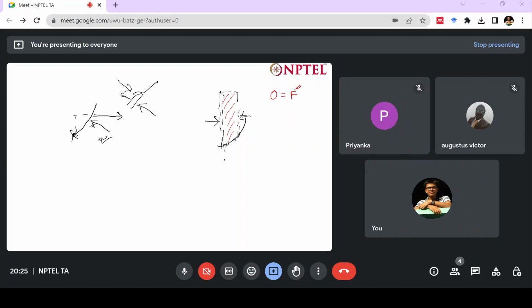One force acting on this is the gravity, the weight. We are not using our Bernoulli here. We are using control volume. If you remember in our expansion of Bernoulli, where does this rho g term come from? It comes from our body force term, right? When we integrate along a streamline, the body force term becomes your rho g h. So we need to take that body force into account.